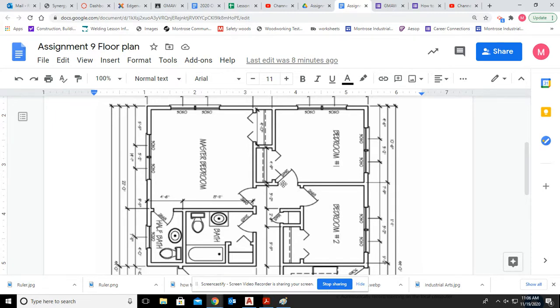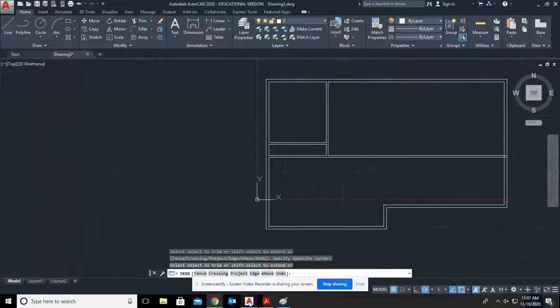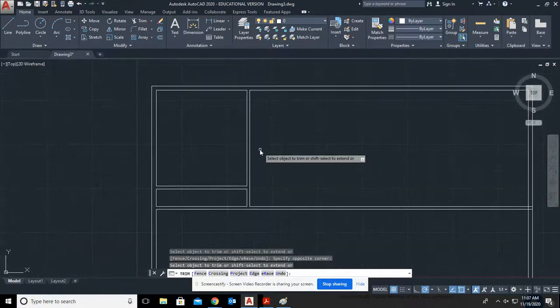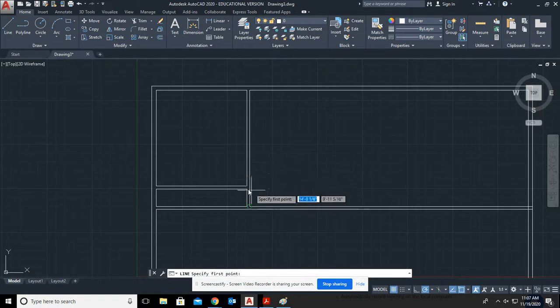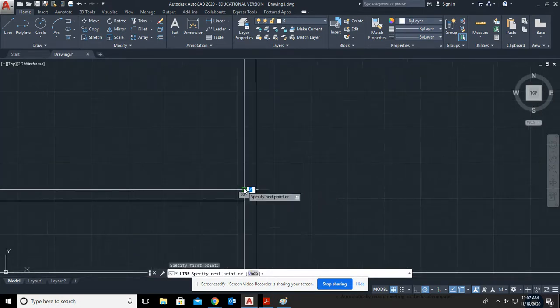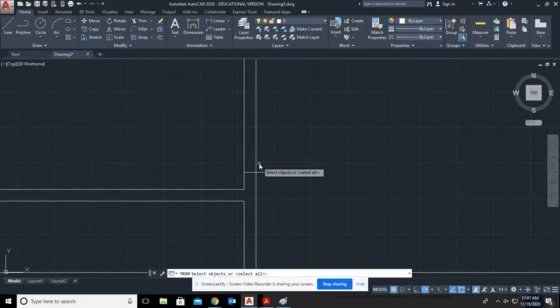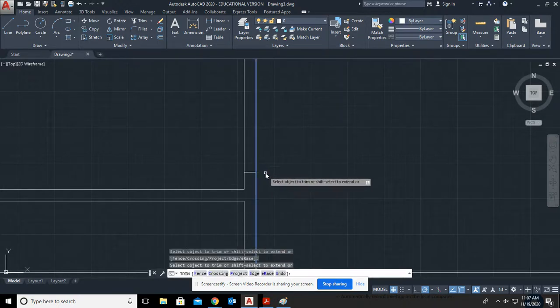So I'm going to show you how to incorporate a door, and how to go ahead and draw this. There's blocks we can add. For now, we're not going to talk about blocks. We're not going to add any blocks. So that door goes right here. We can continue to use the offset tool, or we can just draw something. And I think I'll just go 6 inches, and then come back here. Get rid of that little line I drew. And we'll trim this back to there.